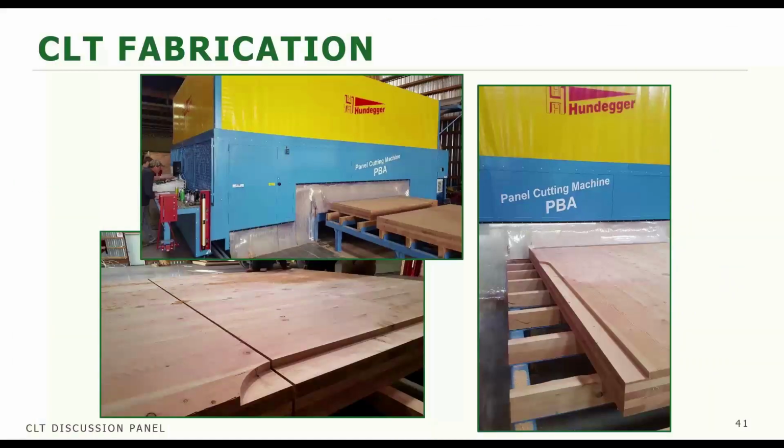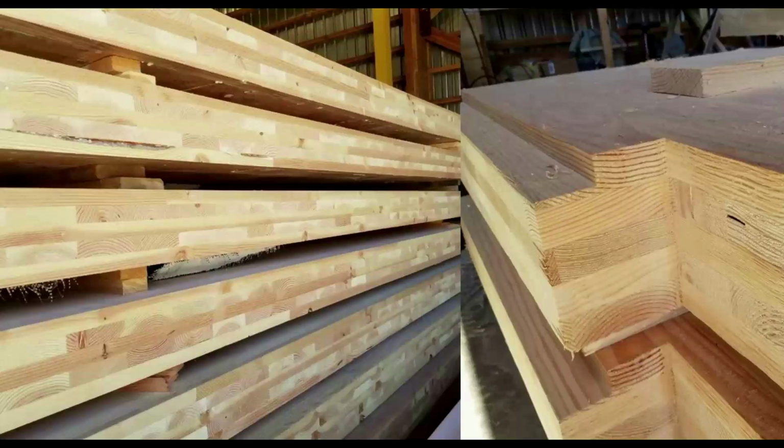We then take those billets and we put them on a CNC machine. And that CNC machine gets uploaded with the 3D model that we created earlier. This CNC machine can do any of the millings, drillings, daps, routing, really any of the wood removal that's necessary for each particular project. You can see the picture on the right has a panel-to-panel connection, like a dado that's going along the length of the panel, as well as a notch. The picture on the left is simply panels that have been trimmed. You can see they're nice and flush, nice tight edge joints.